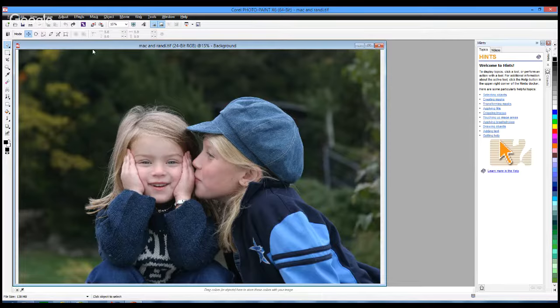But I'm going to give you my settings for the machine that I'm going to practice on here, and hopefully that will give you a little bit better of an idea on how to adjust your machine for the powers. But all I can say is, when you laser engrave, you don't want to go very deep in the material. The deeper we go into the wood, the worse our photo is typically going to look. So normally when I laser engrave, I want to have a very minimal amount of penetration into the physical wood itself, or the acrylic, or plastics, or things like that. If we're working with stone or glass, typically we don't have any penetration, so that's a little bit easier to do in terms of power and speed.